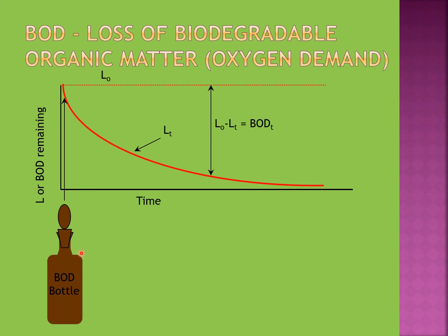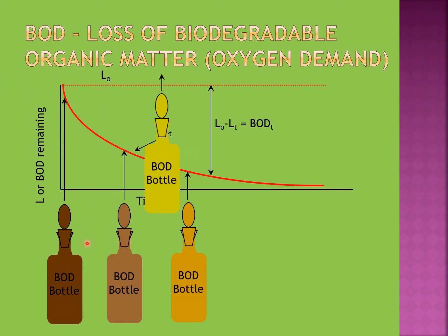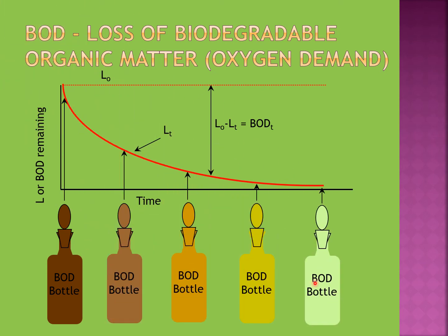This deep color bottle indicates high BOD loading, and this lighter color bottle indicates lower BOD loading. As we know, BOD loading decreases with time, so with time, this lighter color bottle indicates lower BOD loading.